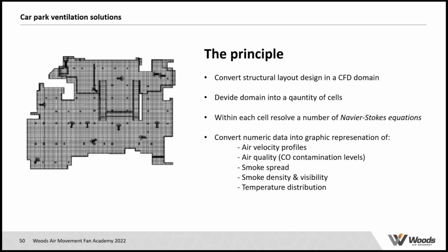I've seen people out there that seem to be capable of doing simulations in maybe half an hour, which probably is doable, but that means that you will probably use bigger cells, so a lower quantity of cells in the domain. That is a possibility. The only downside is the accuracy of the actual flow analysis is dramatically reduced.